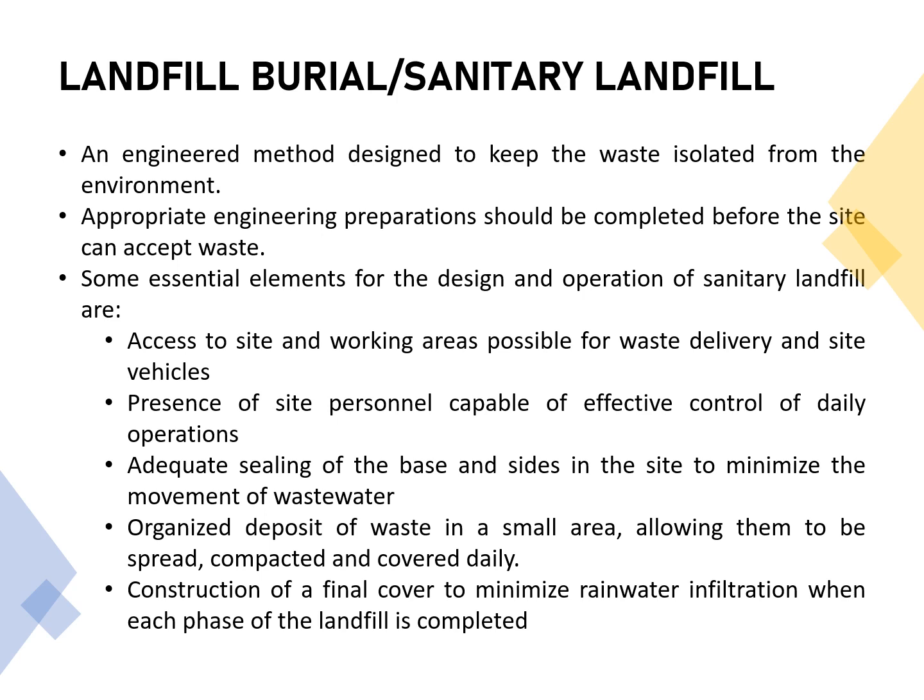Adequate sealing of the base and sides in the site to minimize the movement of wastewater. Remember that if wastewater in the sanitary landfill is not controlled properly, it may leak into other parts of the area where the water should not be found. Organize deposit of waste in a small area, allowing them to be spread, compacted, and covered daily.